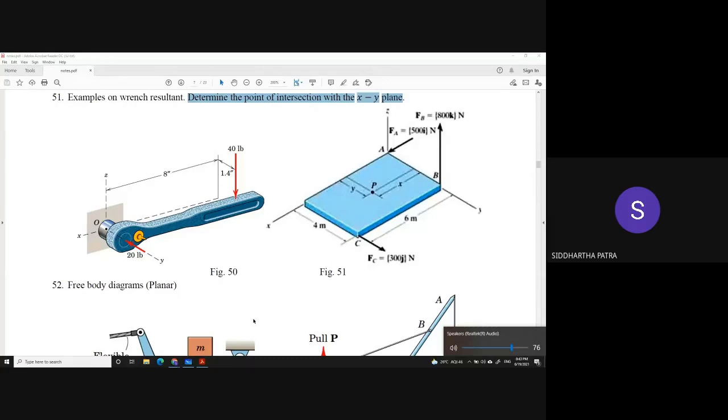So there is no perpendicular component when I'm trying to get the equivalent force system at P. Which basically means the Cartesian components of the moment and the Cartesian components of the resultant force about point P should be proportional, which is mx over rx equals my over ry equals mz over rz.